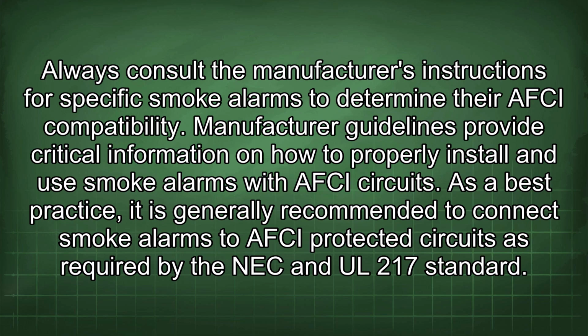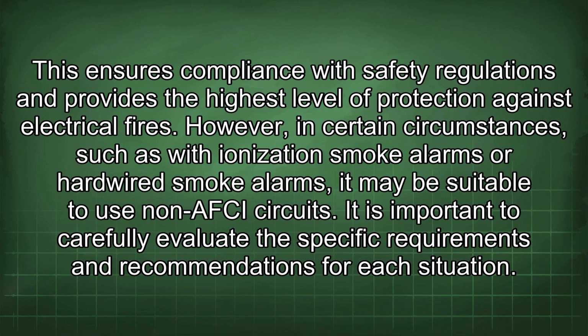As a best practice, it is generally recommended to connect smoke alarms to AFCI-protected circuits as required by the NEC and UL 217 standard. This ensures compliance with safety regulations and provides the highest level of protection against electrical fires. However, in certain circumstances, such as with ionization smoke alarms or hardwired smoke alarms, it may be suitable to use non-AFCI circuits. It is important to carefully evaluate the specific requirements and recommendations for each situation.